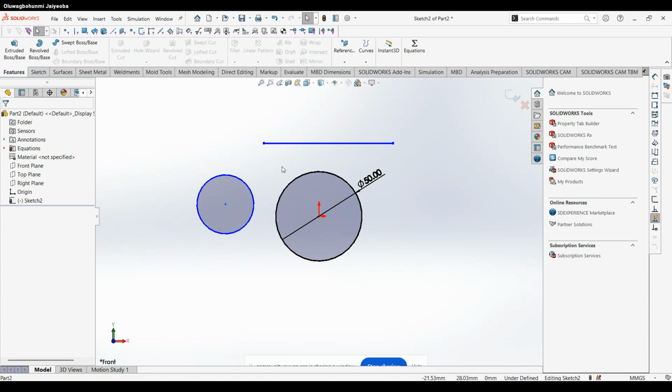So how do I fully define my sketch? I'll make my sketch fixed or constrained to certain dimensions, right? So let's say I want the distance from the center of the circle to the center of the circle to be variable C. That's 70 millimeters, right? If I do that, I want to make them collinear, like it should be horizontal on the same line.